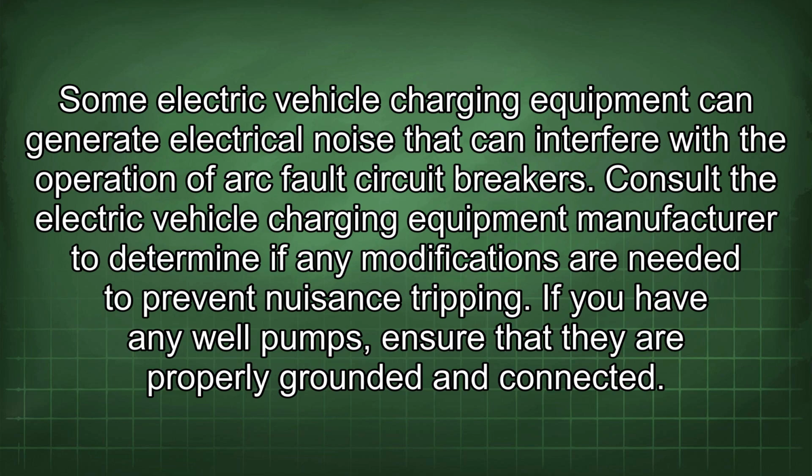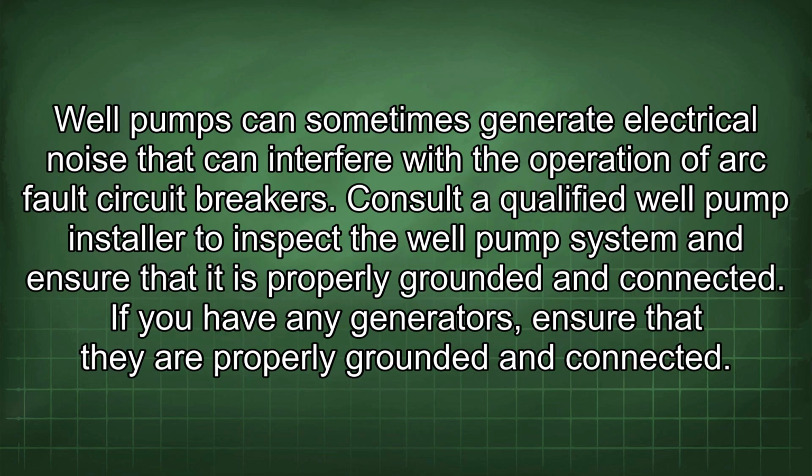If you have any well pumps, ensure that they are properly grounded and connected. Well pumps can sometimes generate electrical noise that can interfere with the operation of arc fault circuit breakers. Consult a qualified well pump installer to inspect the well pump system and ensure that it is properly grounded and connected.